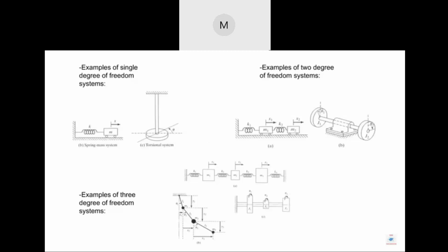In B diagram, as well as the torsional system, 2 rotors are on that shaft in 2 sides, and these 2 rotors are twisted, one clockwise, another anti-clockwise, by angle theta 1 and theta 2. Therefore, to describe that system, 2 angular displacements are required, theta 1 and theta 2. The equation of motion will be based on these theta 1 and theta 2 for this system.